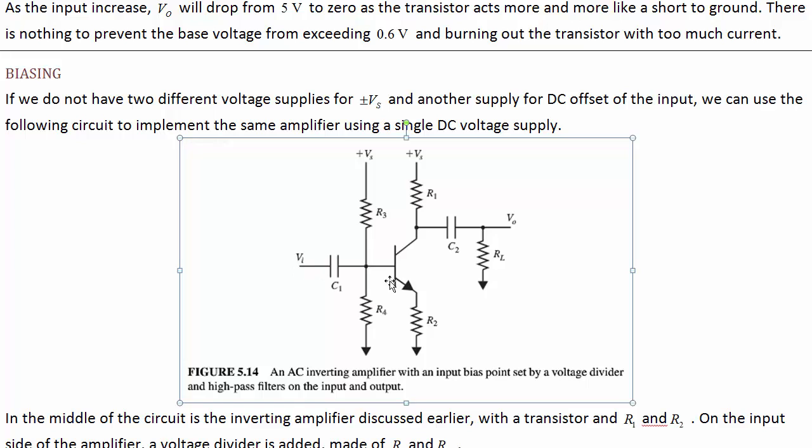So before, we were looking at this perspective and we calculated the effective resistance seen by the capacitor in this RC filter. And we said, okay, let's ignore this impedance because it's quite large compared to these two. And if you want to look in terms of complex impedance, there may be some other effects of what's going on at this output that might be seen on the input, but those are going to be even smaller than this impedance change. So let's just say that the impedance of the transistor is large and see if you can figure that out.